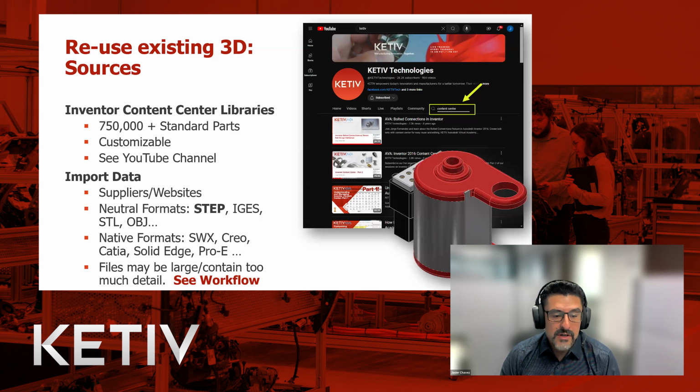And if for some reason your customer has a different tool, they can send you their native format, their native SolidWorks files, Creo, et cetera. In a lot of cases, Inventor can work with that directly. And the one caveat that you're going to want to think of is they gave you those files. It's their part, their design, and they're focused on the details, right? The details of a breaker, the details of a motor that they manufacture and sell to you. And they have a lot of internal components, a lot of little nuances. That is 100% their focus. For you, this might be just a tiny thing that makes up your overall design, and it may contain too much detail.